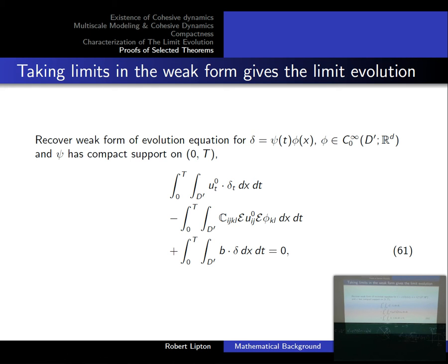And so there are many things that aren't mined yet. I just gave you as much as I know, but certainly, you also know, I didn't show it, that for example the normal traction on either side for every one of these components of the jump set is 0. You can show using test functions. The experts probably can prove it in full generality. I have to assume various things on the set, but then you can show, if the jump sets are regular, then the traction is 0.